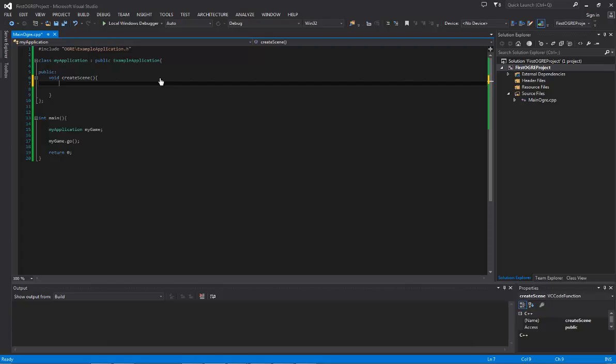And so basically, whenever you have an Ogre app, your scene will have a root, and you can think of it as the origin of your environment, or rather the world, and then whatever entities you have in your scene, lights, for example, meshes, objects, planes, all sorts of things that you have, particle systems, you can actually add them and attach them as children of this node.